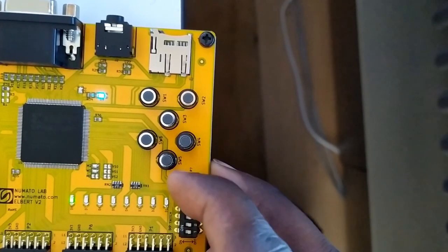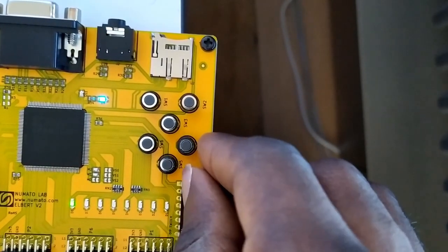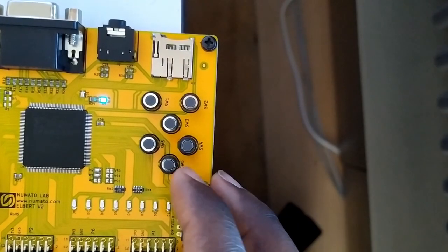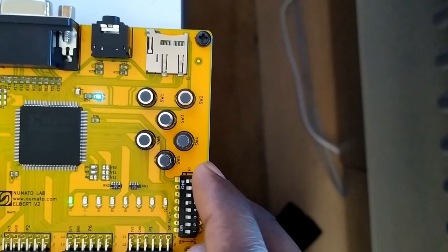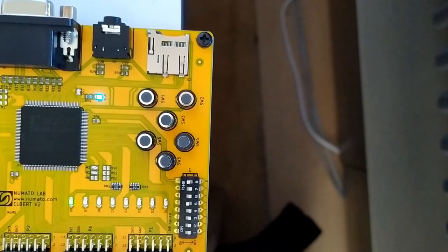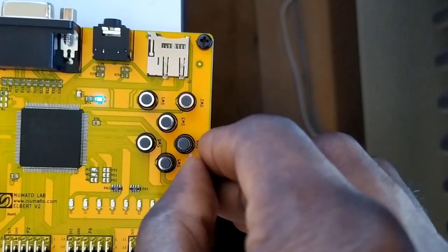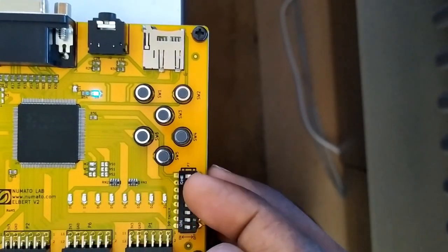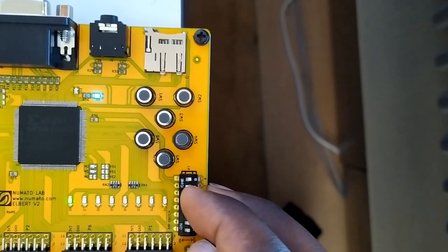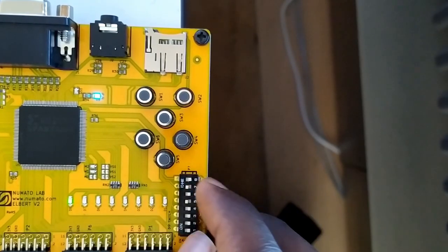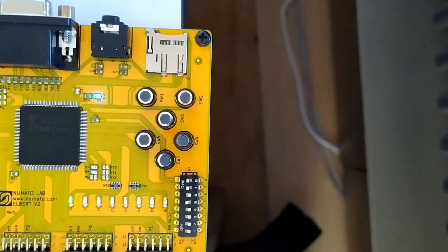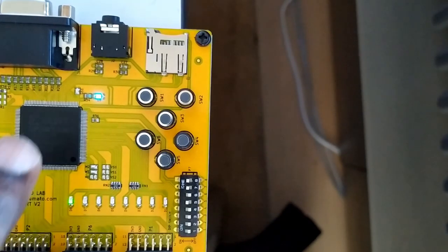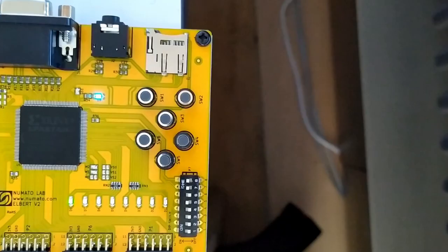So now we're on 0. If switch 1 is on logical high, I have my LED on logical high. If I put it on 0, I have it also on 0. If I put switch 2 on 1, I have the output on 1, and if I put both on 1, I also have the output on 1. So we have just realized an OR gate. Our FPGA board is acting like an OR gate.